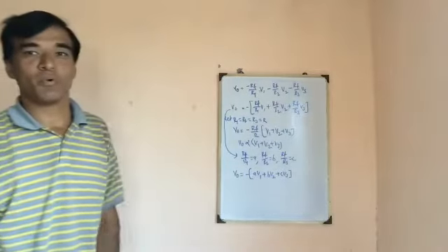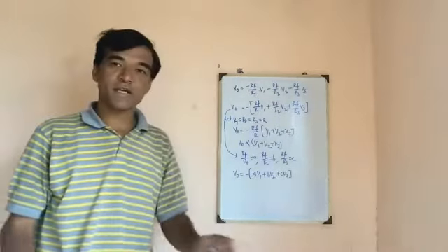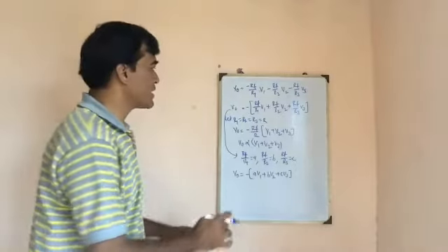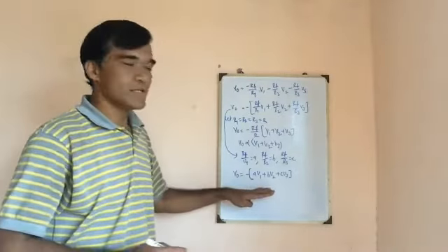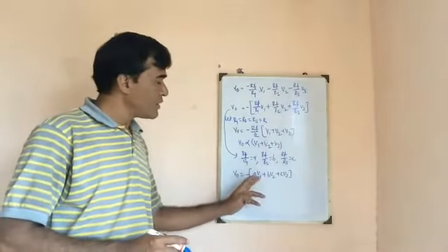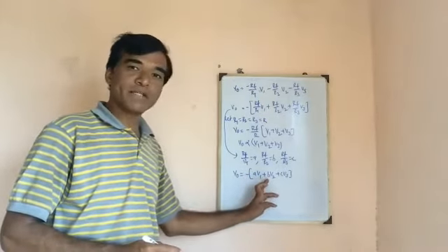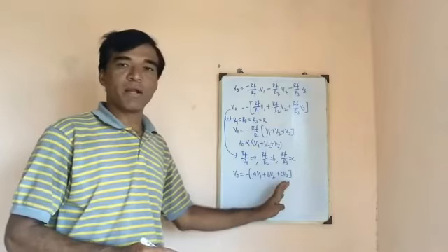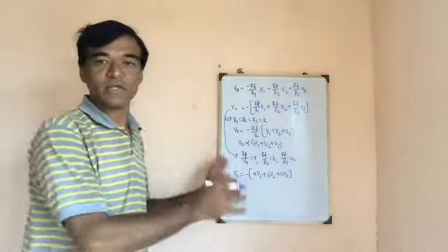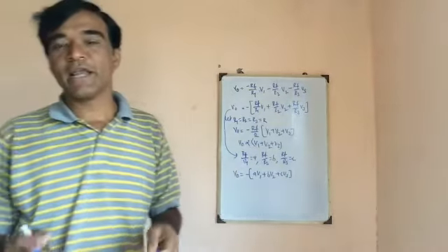Here A, B, C are scalar values. Hence I can consider the same circuit as a scaling amplifier also, where V1 is multiplied by the scalar A, V2 by the scalar B, and V3 by the scalar C.